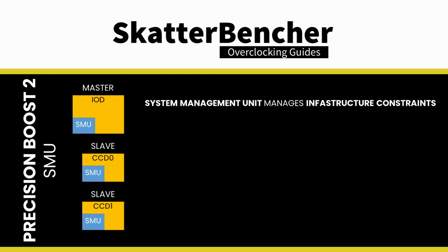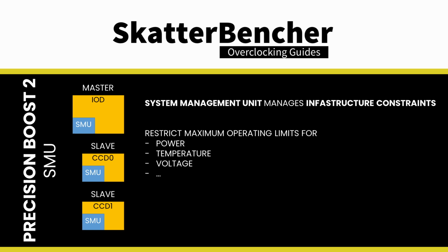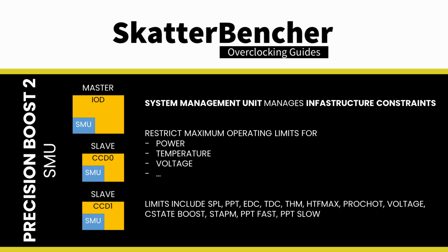The SMU has a range of capabilities, including, most importantly, the ability to manage the CPU performance within the infrastructure constraints. The infrastructure restricts the maximum operating limits on various metrics, including power draw, temperature, and voltage. We don't have a comprehensive confirmed list of the metrics, though some are exposed to the end user. On Raphael, the exposed infrastructure limits include the following. We'll have a closer look at each of these in a minute.